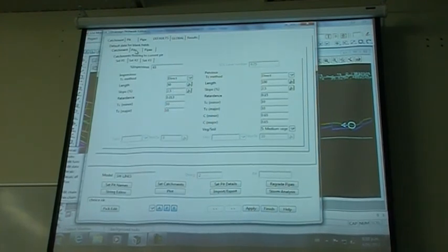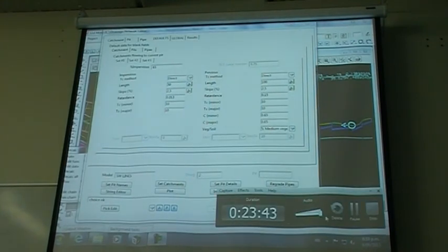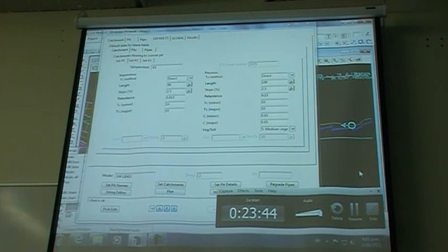So if you set the TC to 10 minutes, what does that actually change in the pipe? Because wouldn't the time be dependent on the slope and the length of the pipe? Yeah, does that change anything? Not really. I'm trying not to analyse too much, but no. It's a fair enough question. What you'd normally do is analyse and work out those times of concentration, but just to keep it standardised so that we get a basic response, so that the figures that come out at the end have some kind of standardisation, we'll just keep to a blanket assumption.